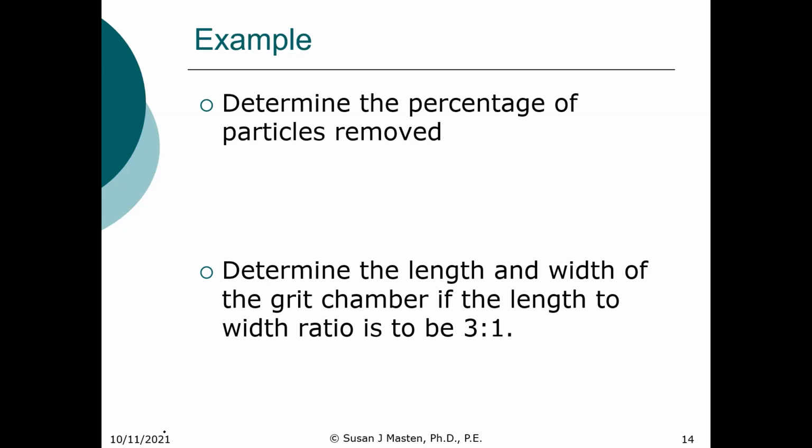So the next thing I'm asking you to do is to determine the percentage of the particle removed. So for a horizontal sedimentation basin, the percentage removed is equal to the terminal settling velocity of that particular particle divided by the overflow rate. And if we were to draw a sedimentation basin,